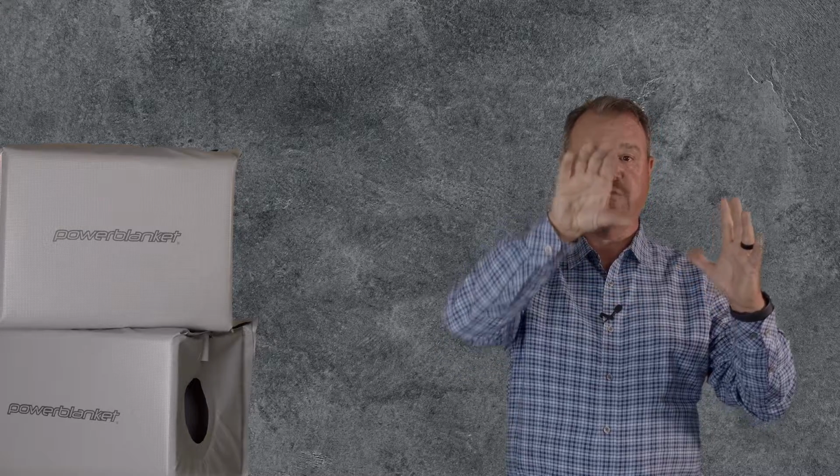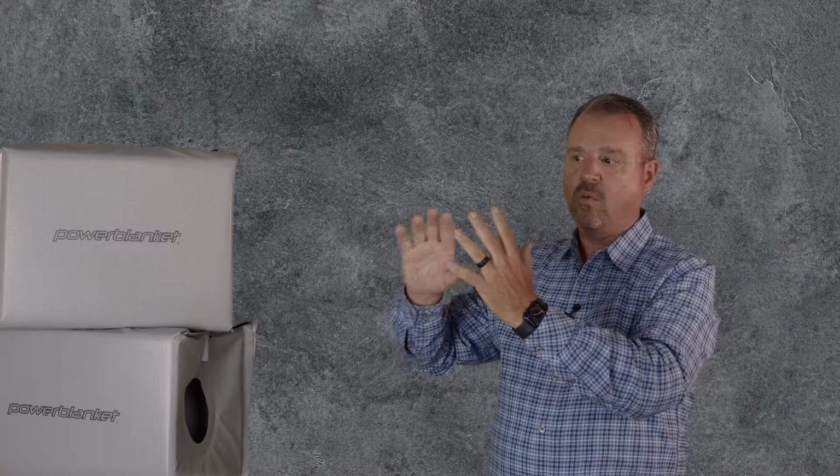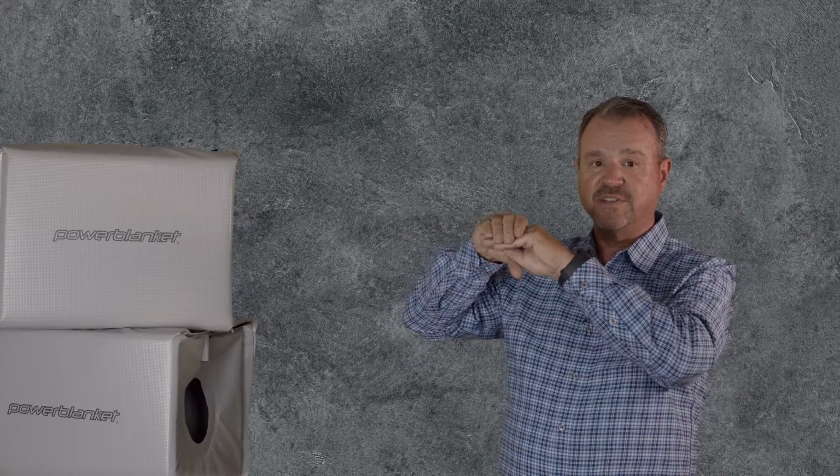heater. With a pipe insert immersion heater, they've actually welded a Schedule 40 pipe or multiple Schedule 40 pipes onto the face of an ANSI flange. Then that whole assembly gets installed inside the tank. What you have are heated wells with heaters on the inside of them,